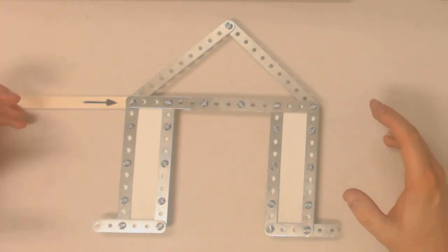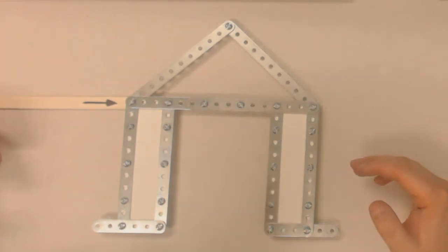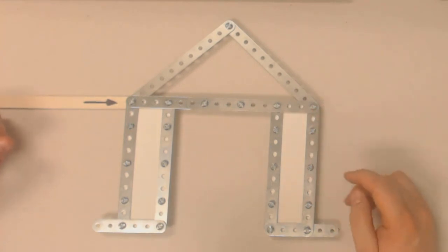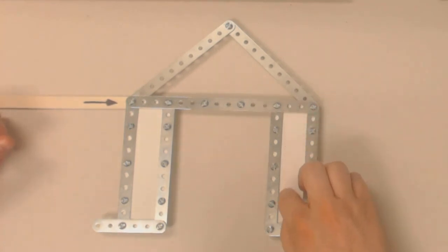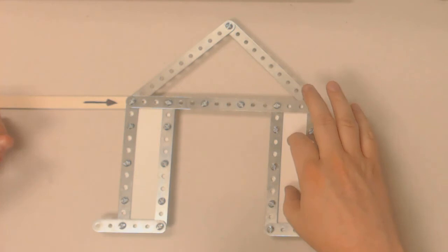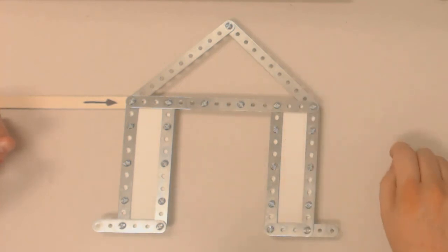So remember, a building is only as strong as its weakest structural component. So if the connections are the weakest, that's what gives. If the inherent strength of the plywood or the sheathing material is the weakest, that's what gives. This will crumple or it'll tear inside, depending on how the forces are applied.